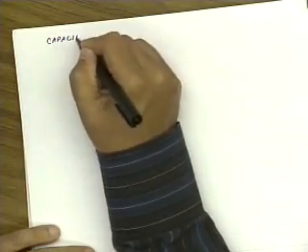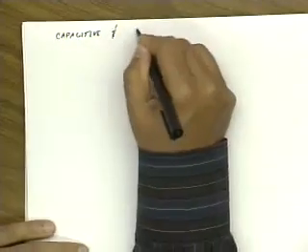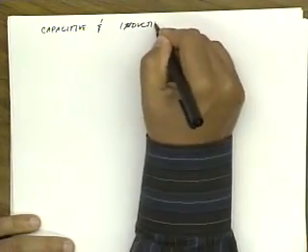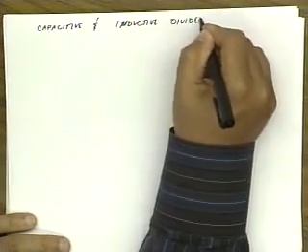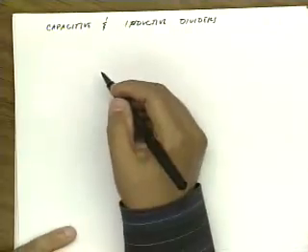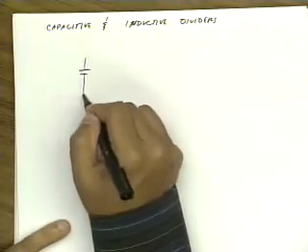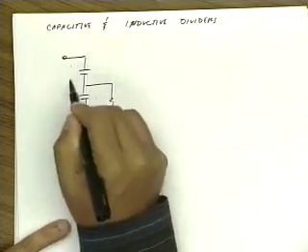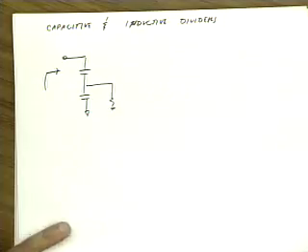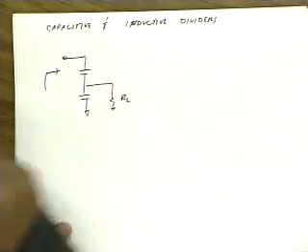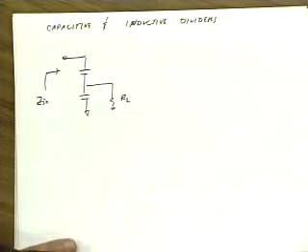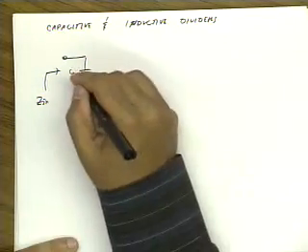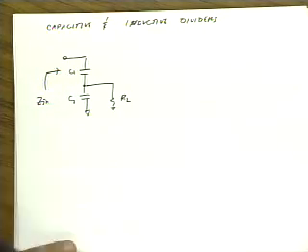All right, so how do we build impedance matching networks? So the simplest impedance matching networks are capacitive and inductive dividers. And the idea is, let's say this is RL. What's the input impedance looking into this network? Well, this is a very simple circuit. Let's say this is C1, C2.